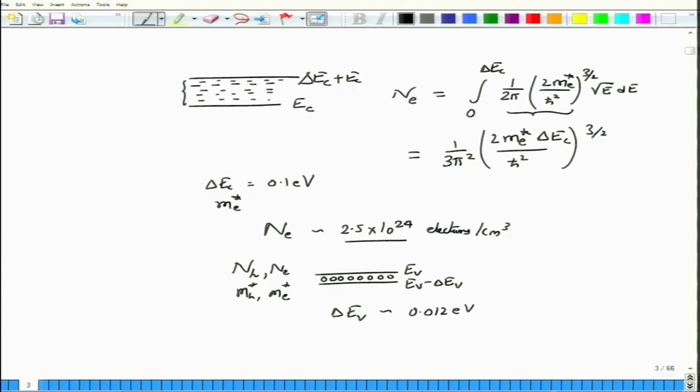So, you normally dope your semiconductor laser diodes with larger values of N doping compared to the values of P doping. Okay. So, what we see is that for the same charge concentration, delta EV is smaller compared to delta EC.